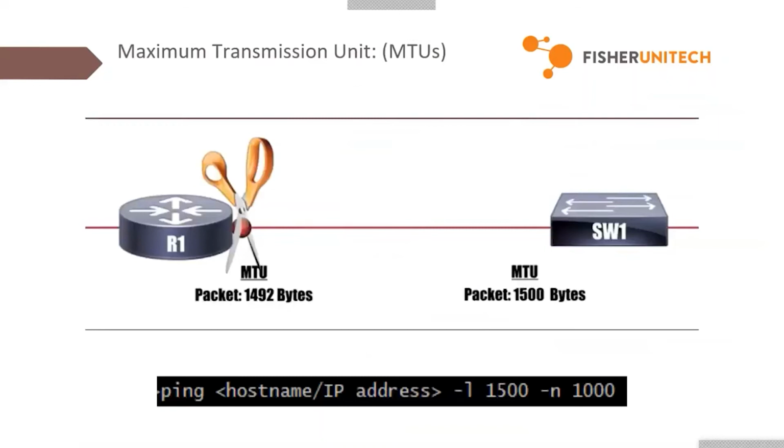There's a term called maximum transmission unit, which is a network configuration for your network devices, like routers and switches, which stand between the clients and the servers, that allows packets of certain sizes. I found that for PDM to work correctly, and I suspect Electrical too, it has to allow packets of 1,500 bytes.